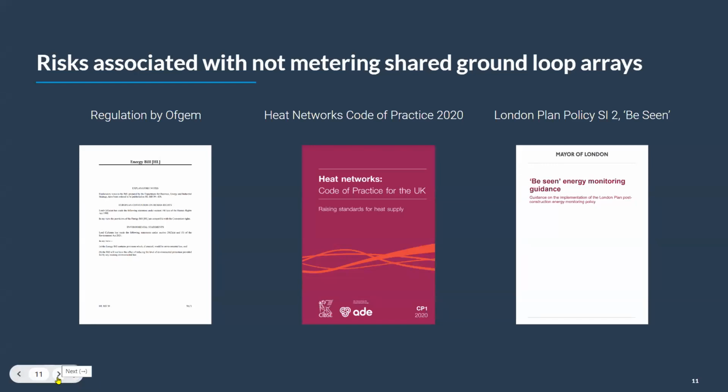So we agree. We think that capturing data every 5 minutes allows you to spot problems when a heat system is in different modes, such as domestic hot water, space heating, or standby. And if we're looking at what this means for ambient loop networks, 5-minute data is the most reliable way to estimate coefficient of performance, or COP, in heating and cooling modes separately. Jack will talk about COP in a moment.